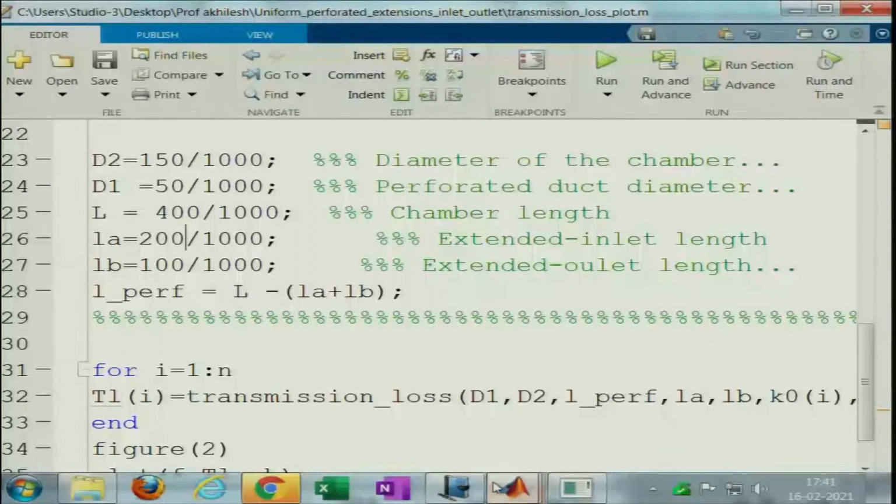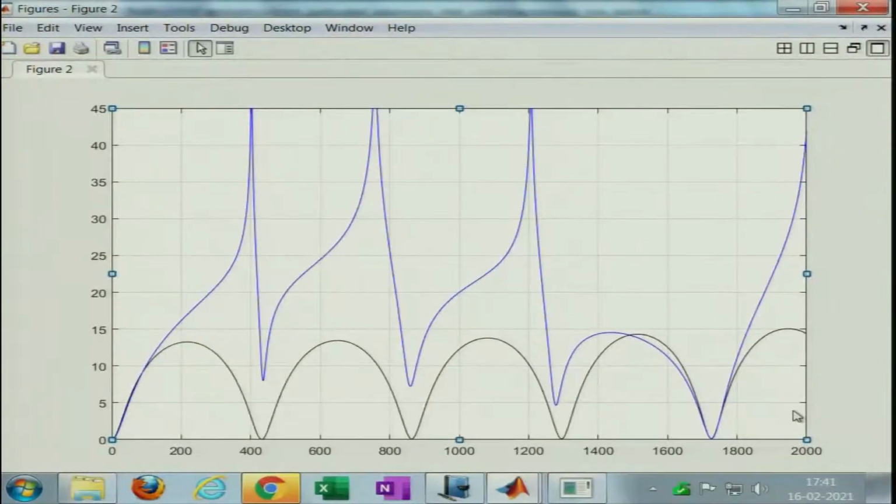So, remember, based on the plane wave model, we are having the peak at this particular value. Okay, and this is happening slightly before the trough. That means what the perforate is doing is that its effect is to basically increase the acoustic length. So the resonance will occur a bit before.